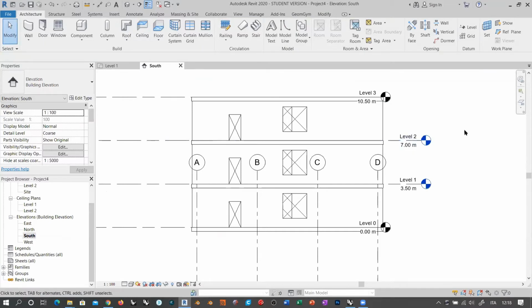So that's why they already have the corresponding floor plans associated, level 1 and level 2. So that's why you have this blue symbol. These are the imported symbols, the imported levels, the new levels. They are black because Revit is receiving this input from the outside, and it was not created inside Revit, so there is no automatic connection with the floor plans.